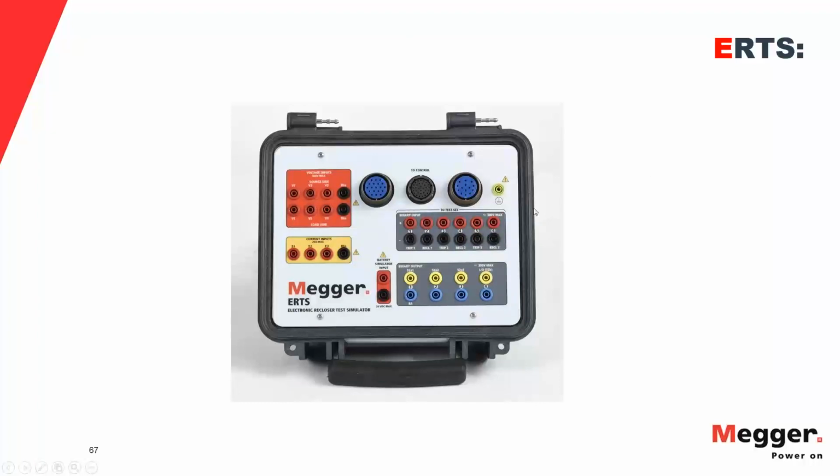You can also use the binary inputs and the binary outputs to simulate the status of the breaker and to get signals from the relay and into the test set, or you can use the cable connection to the tank to bring signals from the controller to the tank.